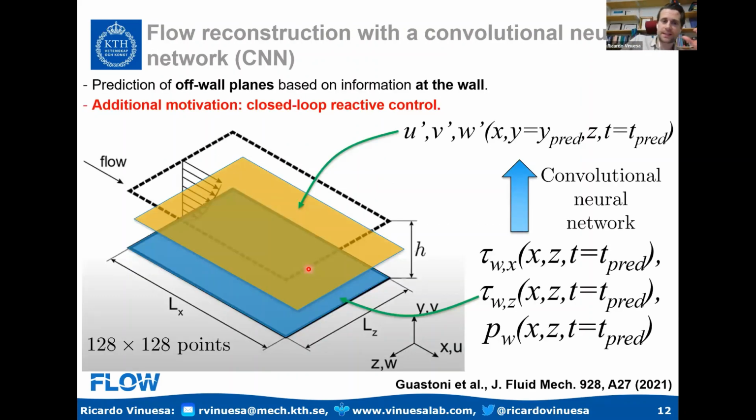Non-intrusive sensing is basically what we can use to, for example, measure at the wall of a turbulent flow and sense what's happening above the wall. So we're actually not using a sensor to perturb the flow. We're measuring indirectly at the wall, and we're predicting what happens above the wall. And that's a little bit the idea.